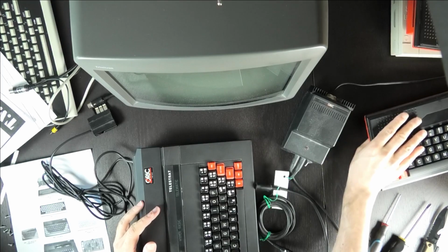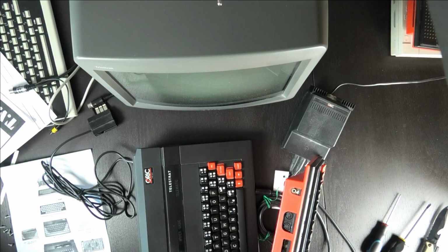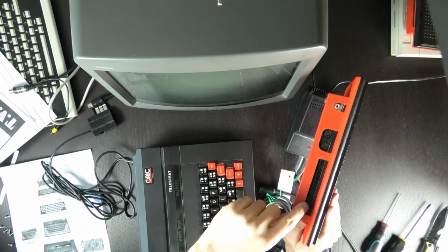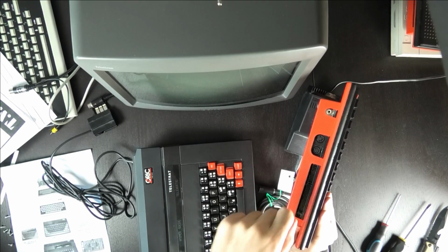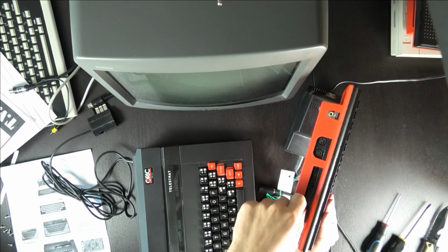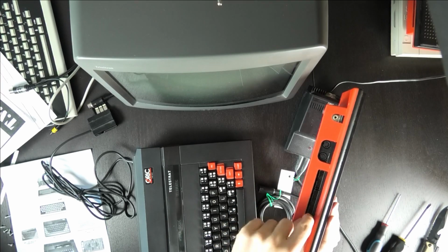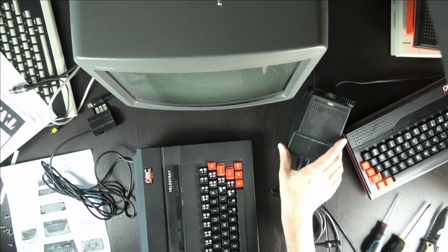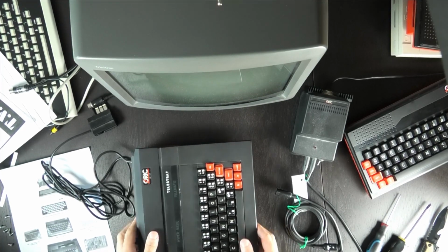It's similar to the decision of putting the power input close by the expansion bus. If you unplug, plug, and do it just 1 centimeter on the side, you're going to burn the Oric, because you connected the +9 volt on the +5 volt pin of the bus. So yes, that is not super smart, and that's one of the many things I don't like in this machine.